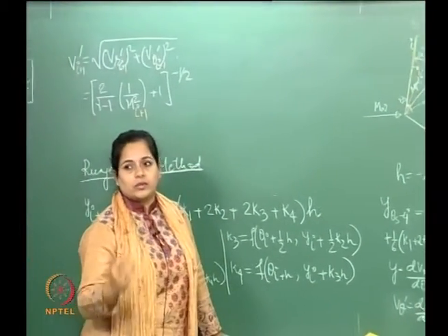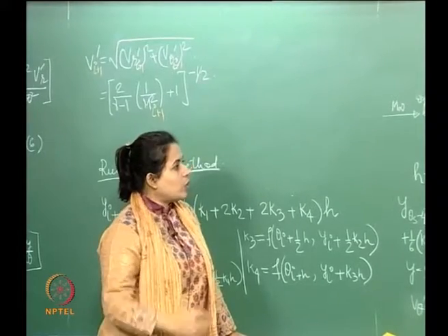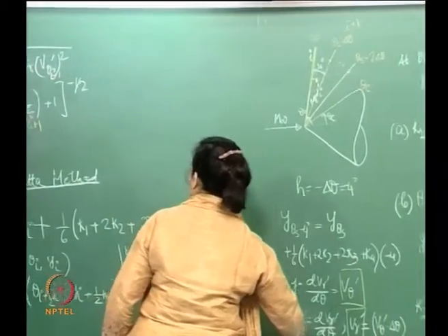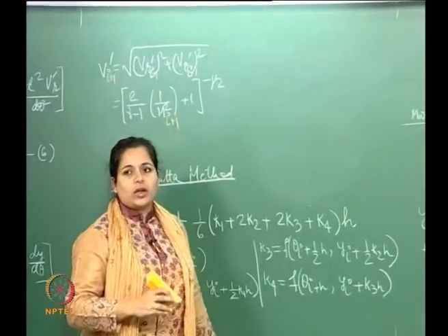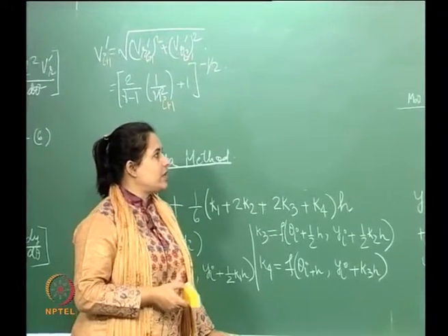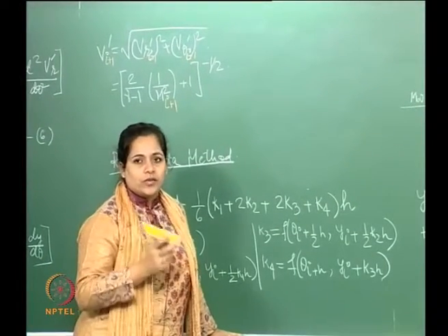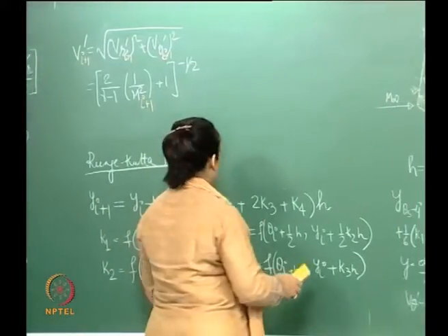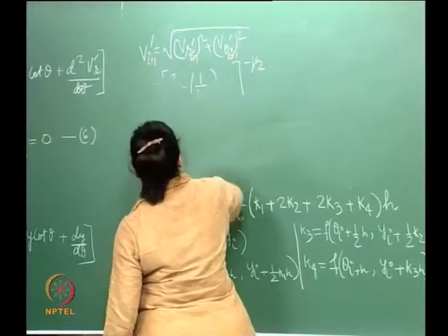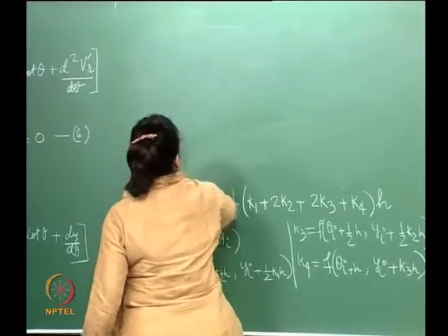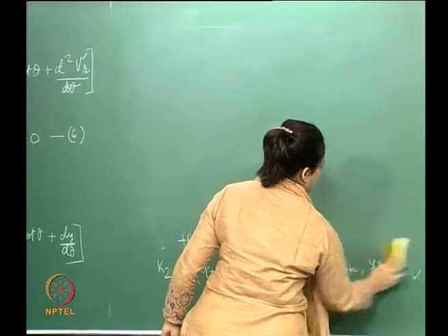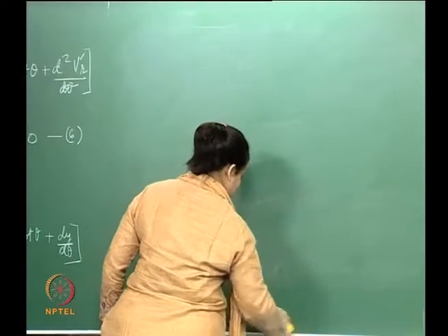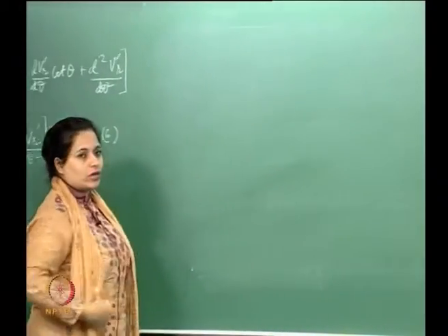How would that look for a cone? For a 3D cone the shock is weaker than that of a wedge, for the same theta c and the same Mach number. You should be able to get properties from your numerical values and cross check.